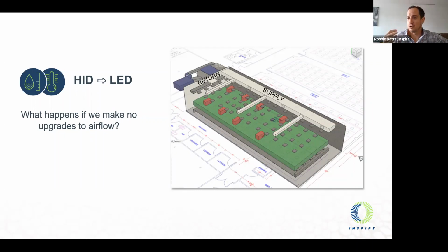I don't think there's a need to scrap and start fresh. Maybe there is. Maybe you just don't have the physical space for it because the equipment would impede on the growing room itself. So you're going to want to keep that in mind. If you were short before, you're definitely going to be short after. A wattage match is going to end up in a situation where you are still lacking capacity because the intensity of the lights is increased. You're going to get so much more biomass inside that room than you would if it was just a PPF match.